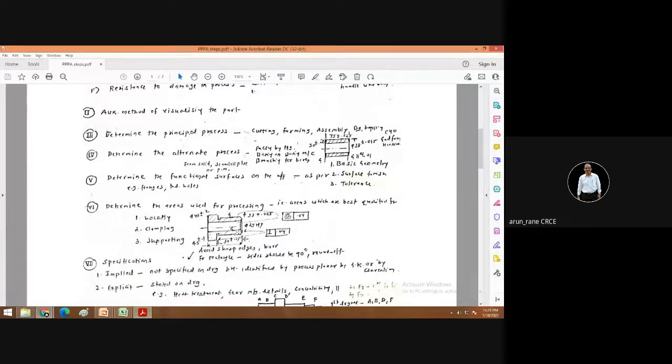And you want the OD to be concentric with the ID within 0.04. That means obviously you will have to locate on the bore. We have to do this OD grinding with respect to the bore. Then only it will be concentric within 20 micron or 40 micron. That means you have to do this in one setting. So here the location has to be the bore.